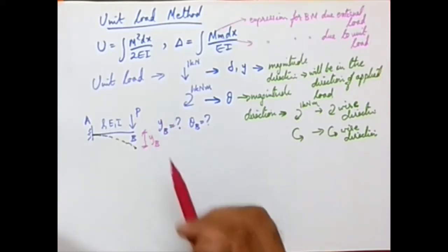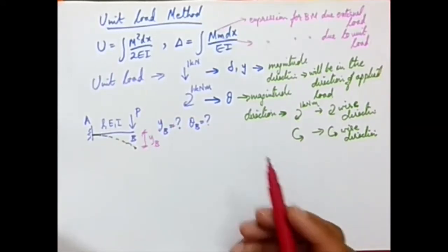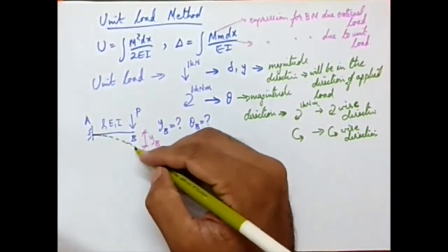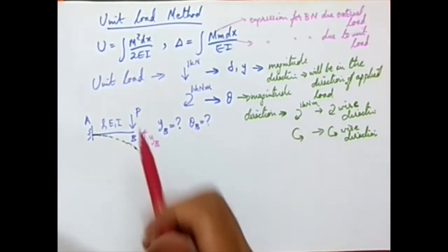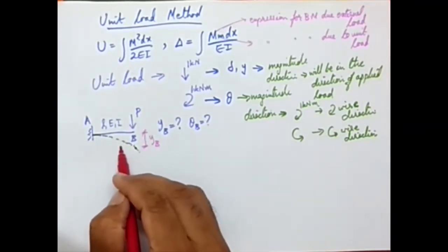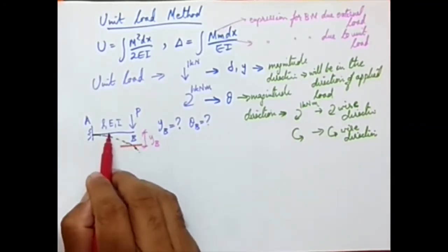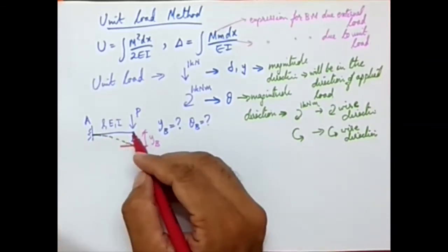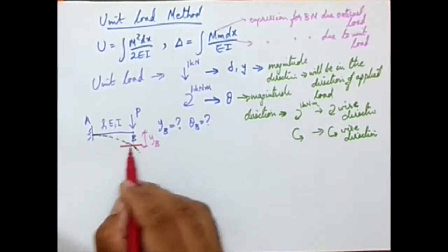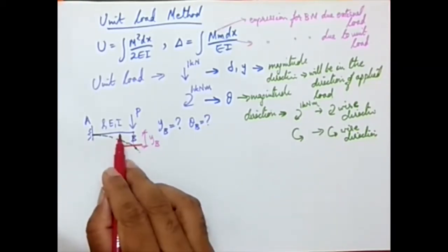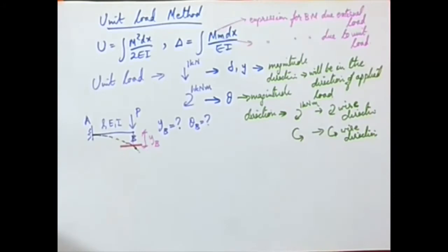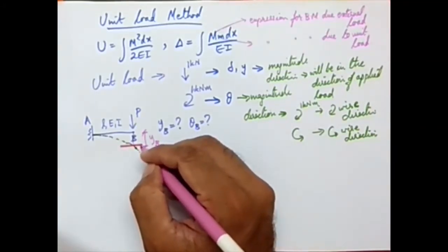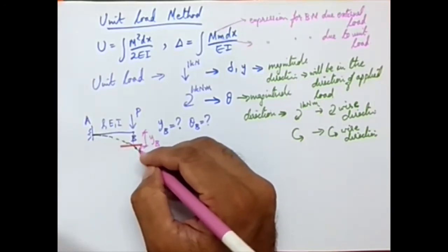When you want to calculate the rotation at a point, say point P, I will just extend this. At point B, I will be drawing a line parallel to the original beam, and the direction of rotation is from the line that we have drawn to the displaced profile.